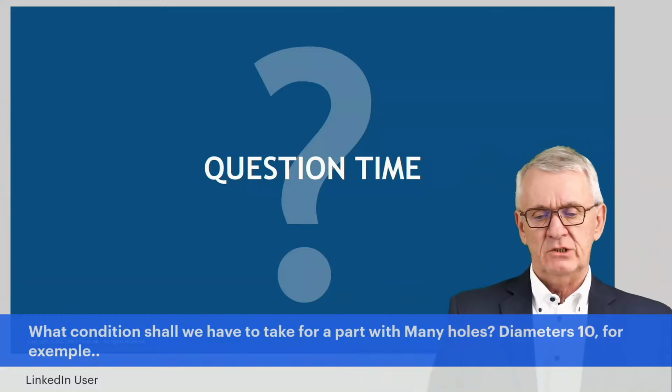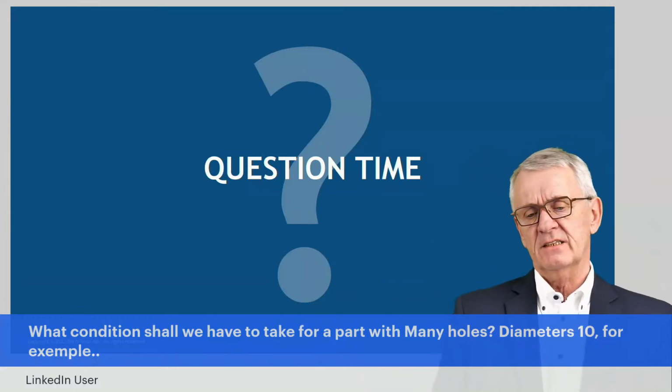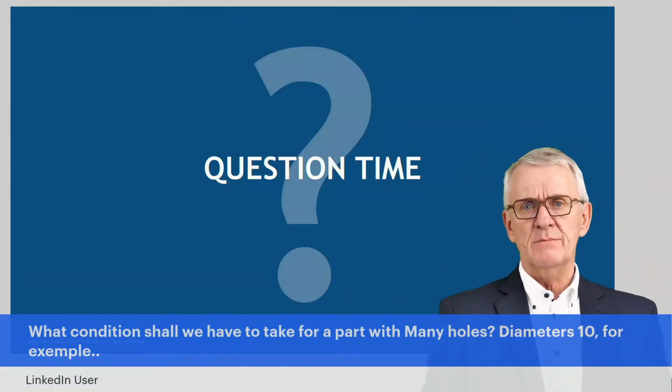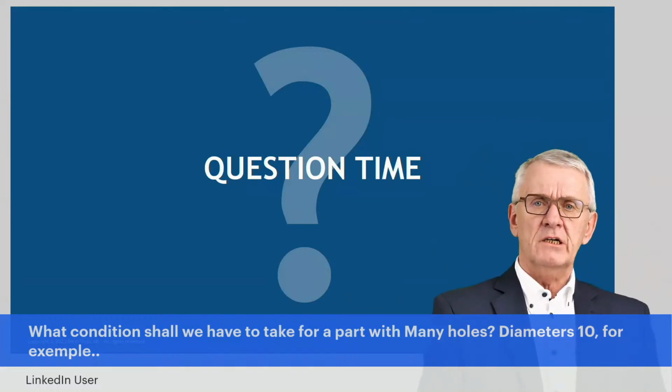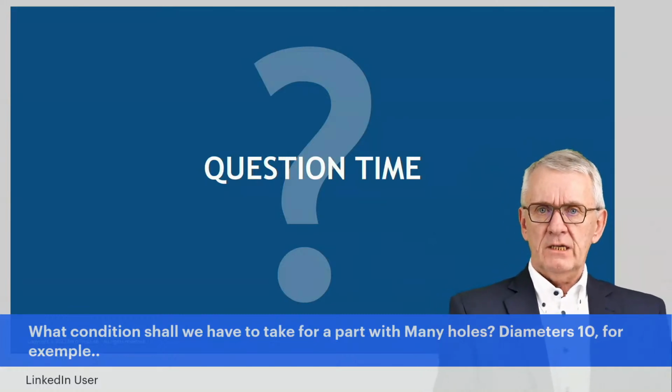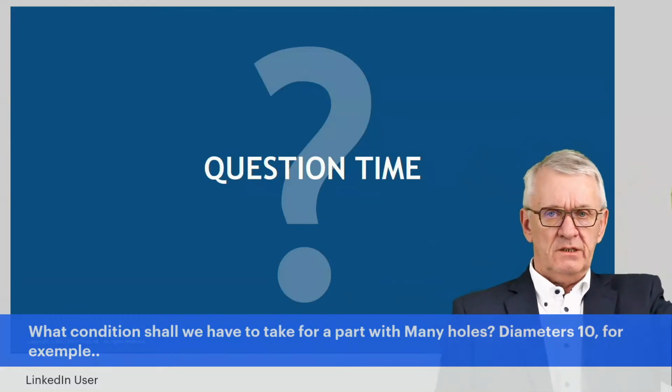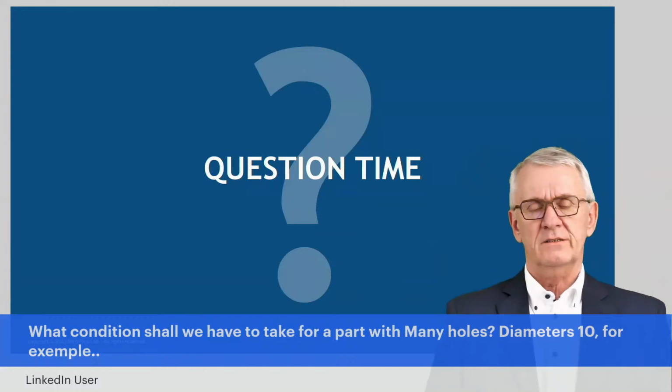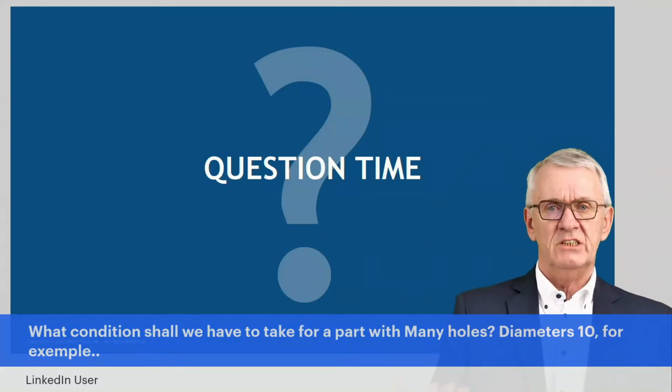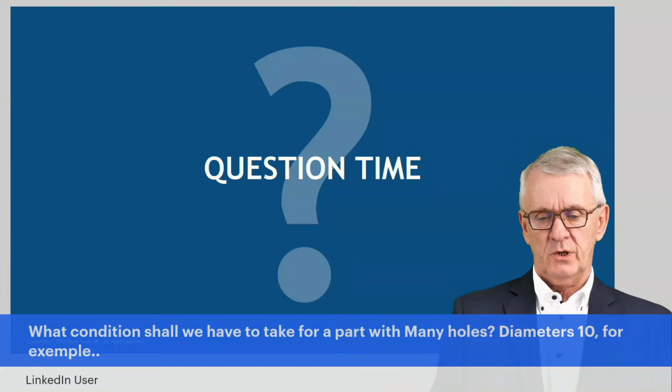Which one will lead to the best result? Again, I can't say here, but I would say think smaller diameters and think numerical control machining, where you can program the milling path such that each time again you have the best possible approach.